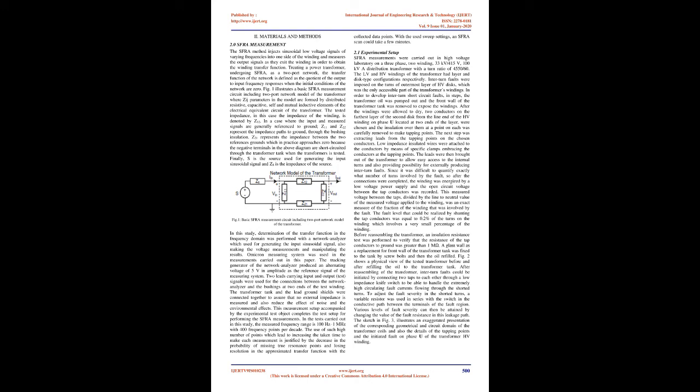In recent years, the applicability and sensitivity of the SFRA method in evaluating mechanical integrity of core, windings and clamping structures within power transformers has been extensively tested by means of fault simulations in laboratory and real case studies of transformers on site. 7-13. A literature review indicates that all of the contributions pertinent to the present study have concentrated only on inter-disk type faults and find it enough to show the overall changes of the frequency response of the transformer as a result of faults. 14-18.